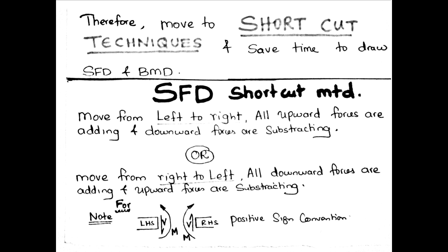Or move from right to left: all downward forces are adding and upward forces are subtracting. For this sign convention, these are the shear force diagram techniques.